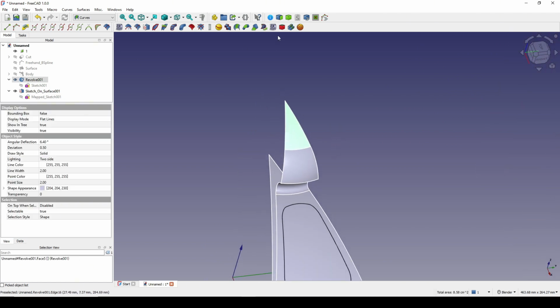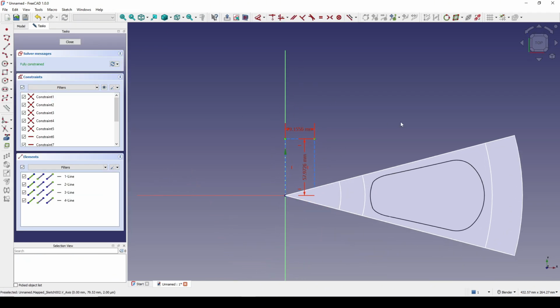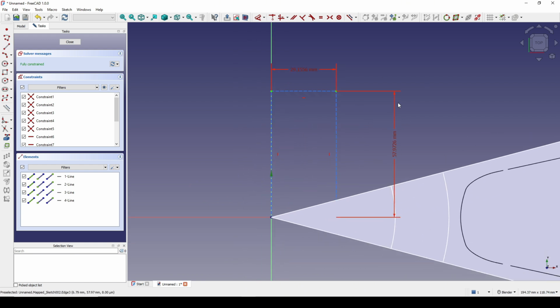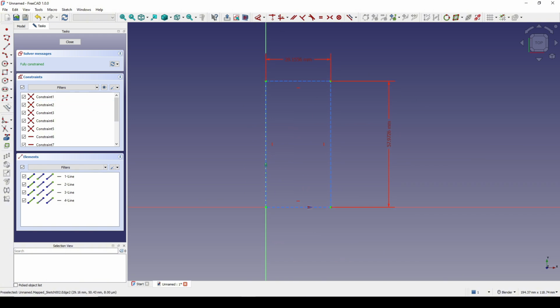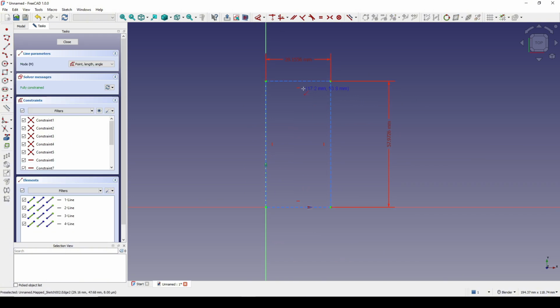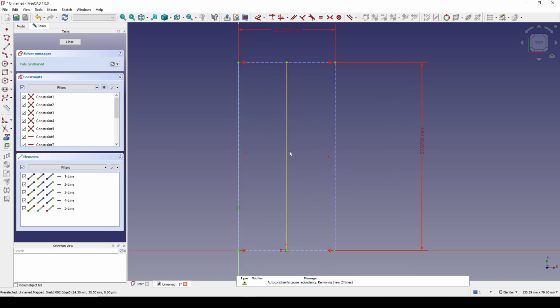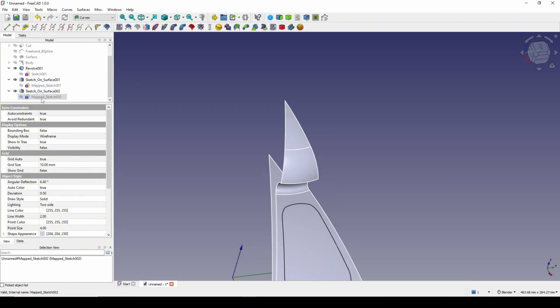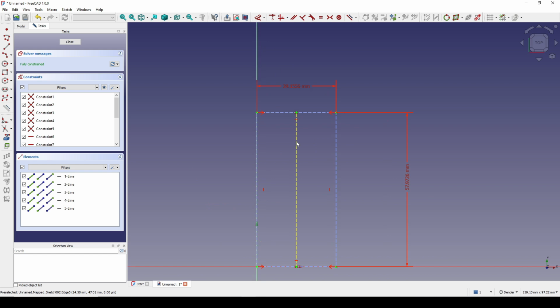Now it's time for the tip. Let's go up here and create another sketch on surface and go inside the map sketch and view the section for that. View the section. Create a line in between and turn that into construction geometry by hitting the hotkey G and N. Close. We go outside and go inside again to see.